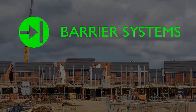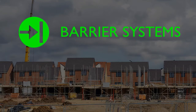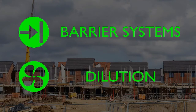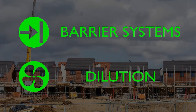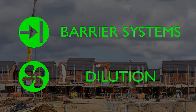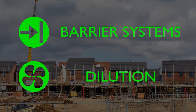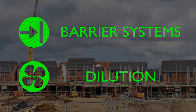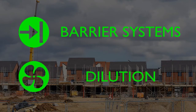Firstly, barrier systems, which physically block the passage of harmful liquids or vapours either at the source or the receptor. Secondly, dilution or dispersal, where ventilation systems are used to reduce vapour concentrations below harmful levels. Ensuring barrier and ventilation systems work effectively over the lifetime of the building is critical. Both specification and installation of these systems is more complex than it may appear, with an array of physical properties, tests and installation details to consider.